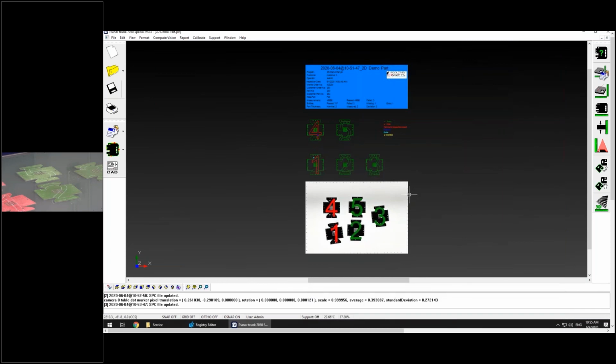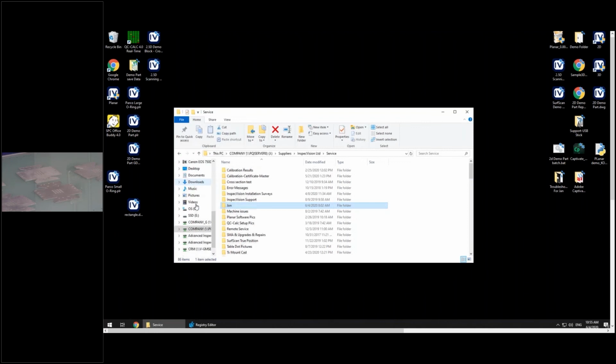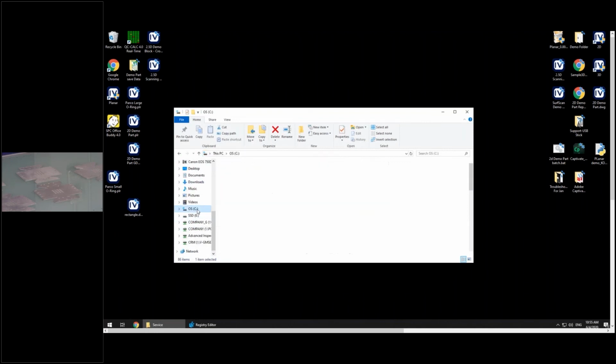And last but not least, for those that have some really complex GD&T, I know there's a couple of you out there. Some of our software just isn't good enough for what you need to do. Like I said, if you have a bolt hole pattern held to a maximum material condition, and that's going to be your datum B, we just can't simulate that. It's nothing Planar can do. Not to mean that you're completely hosed, though.